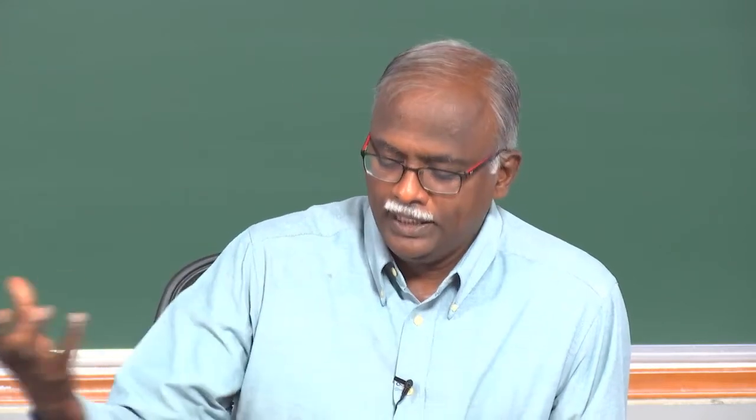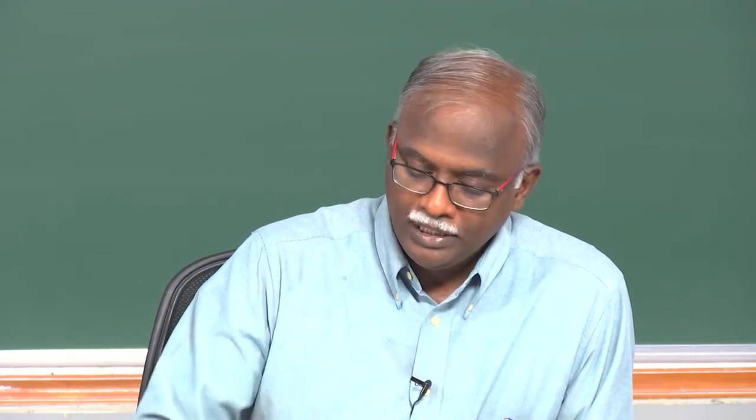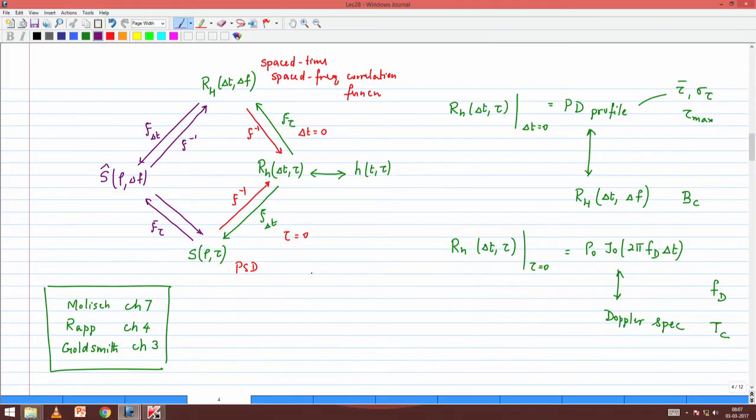So keep in mind that there is a time varying channel response, we have taken the autocorrelation function, and then derived two very important elements from which we are able to obtain the following characterization of the channel that we are working with. The characterization consists of the following: a coherence time, which can be written as 9 by 16 pi fd. So that depends on the Doppler side. Again, as we indicated, that comes from the time variation, which comes from RH of delta t.